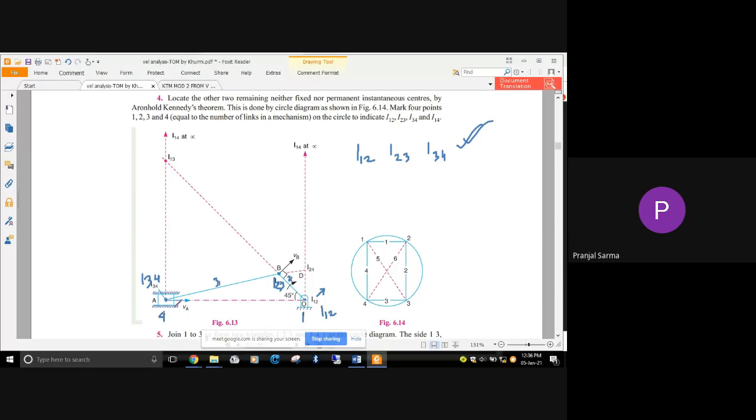It has got sliding motion along the line of stroke direction. That means the line of stroke direction is this much. If this is A, the slider is denoted by A. Then V of A will be in this particular direction. This is V of A, the direction of VA, right?